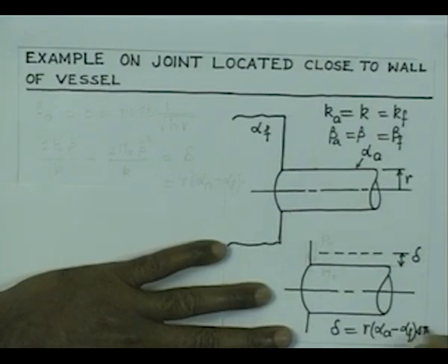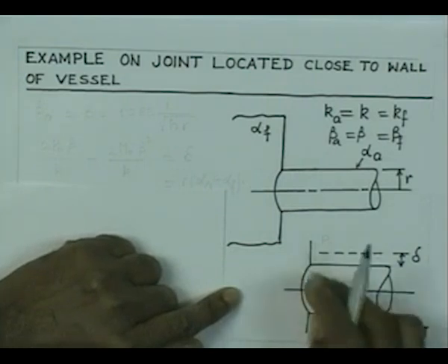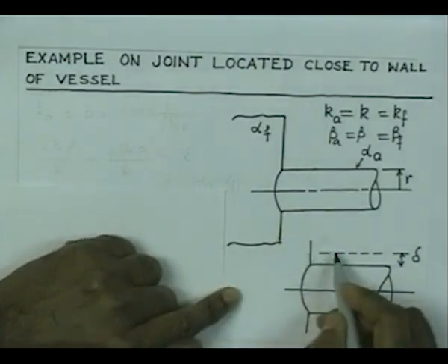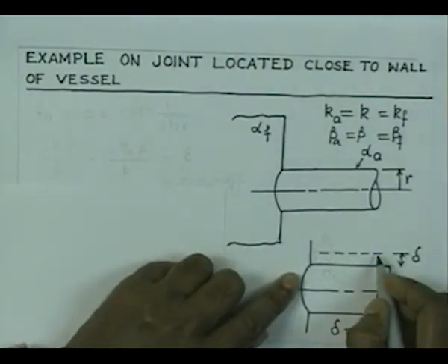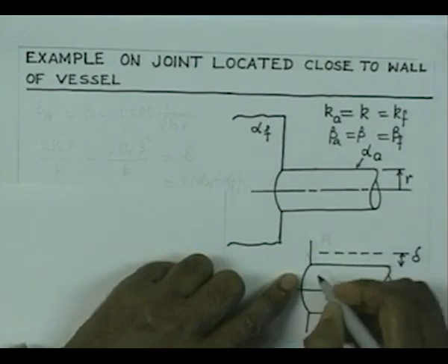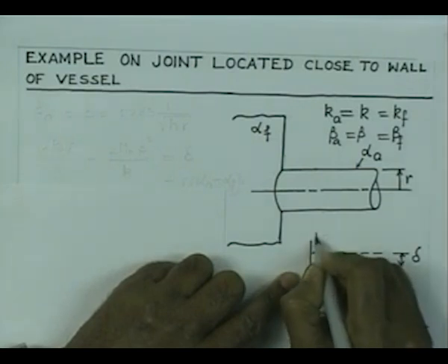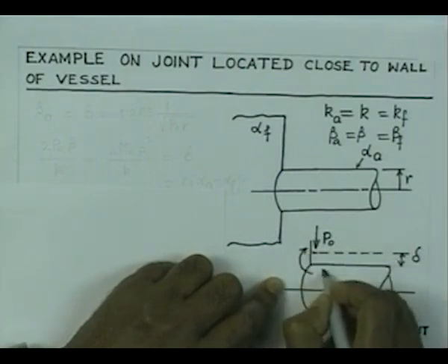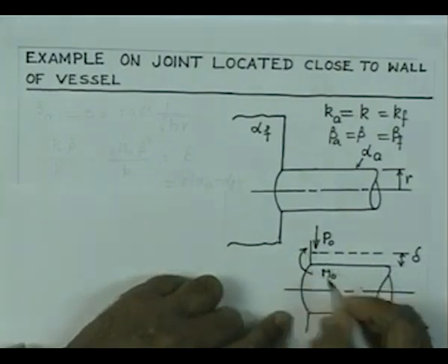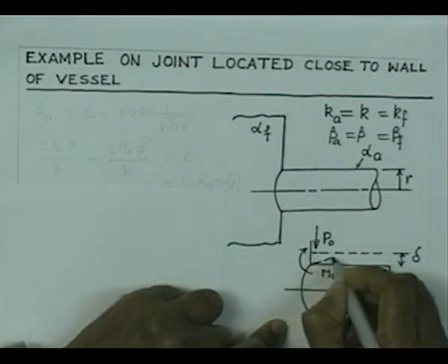So, that is the expansion, that is the differential expansion. Now, the vessel is going to be very rigid in this direction, and because of this expansion, as if this is a rigid body and this pipe is going to expand, it will be arrested. Finally, forces will develop at the edge of the pipe to prevent its expansion here, and there will also be a bending moment developing here to again cause the angular match. So, you will find that this vessel is now going to take up a deformed position like this.